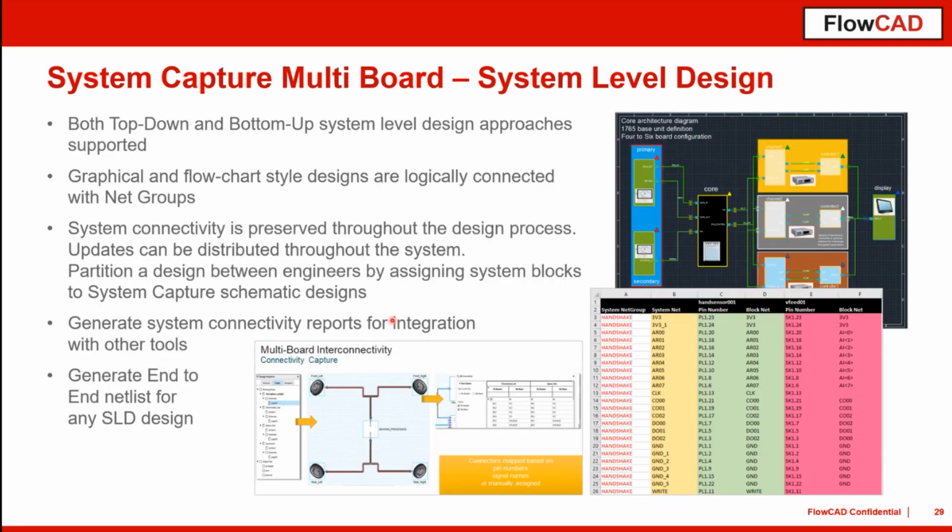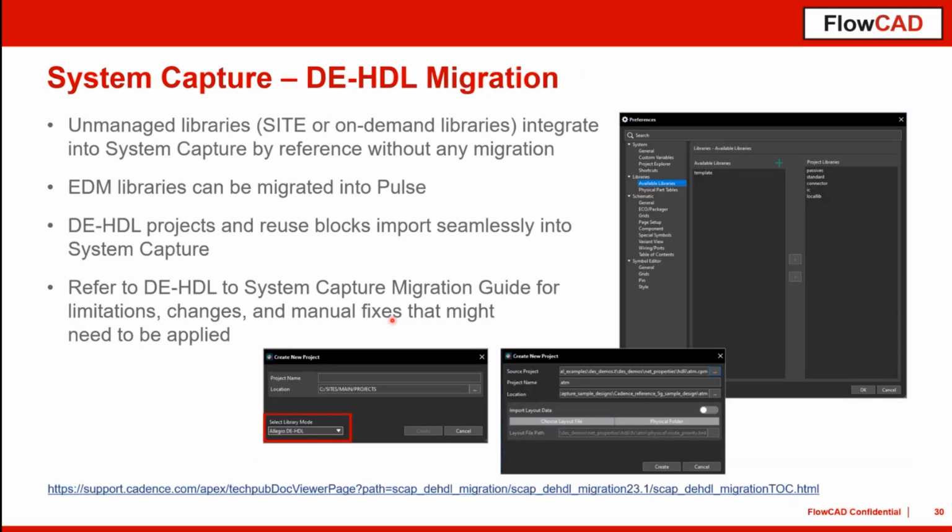Good. Yeah, this is maybe a special case. I don't know if many of you are really using this. Simply keep it in mind that our System Capture also offers the possibility to design system-level designs. So you have multiple boards, and can define the connectivity and interfaces between these different boards, and then the tool will take care that the connectivity is fulfilled as you want it. So system-level design inside of System Capture.